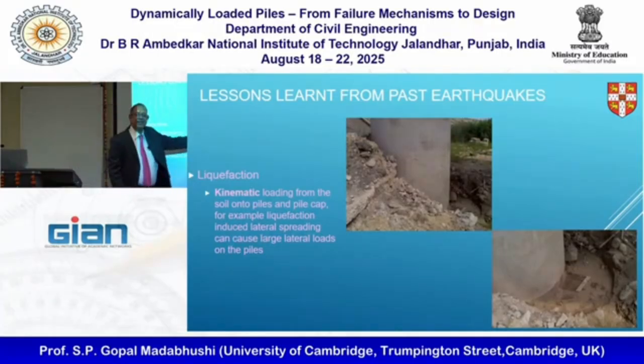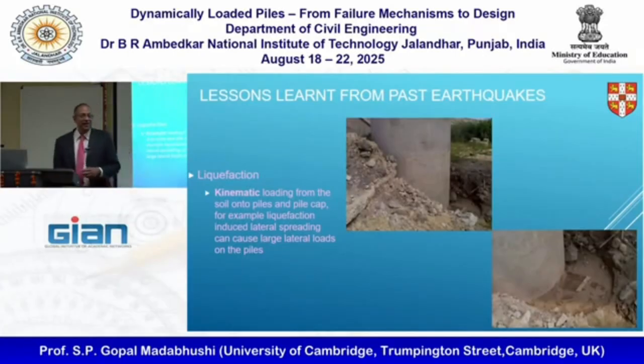But the one that is coming is going to come with Kp, which is roughly 9 times larger than the active earth pressure. If you take phi as 30 degrees, it's 9 times bigger. So the horizontal loads that your pier is going to see because of this will be huge. Even if I had 2 meters of soil, 2 times say 15, to keep the numbers simple, 15 kPa is 30 kPa. That's my vertical stress. Multiply that with a factor of 9. That is how much horizontal stress I'm going to get. And you integrate that over the area of the pier, the load will be significant.